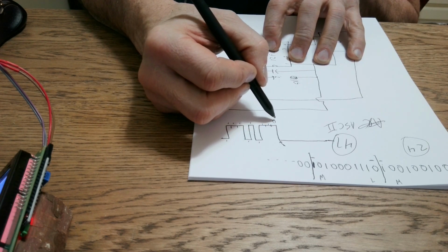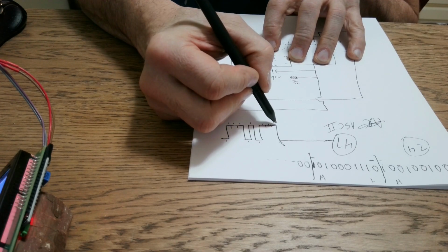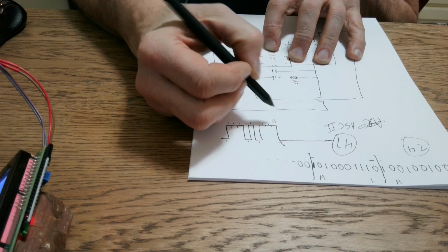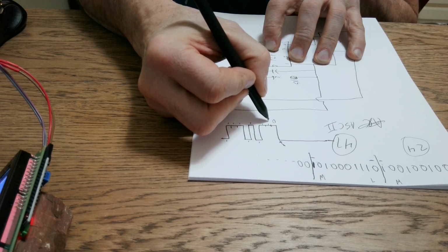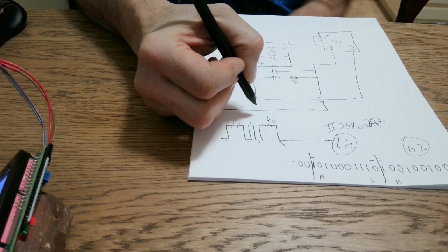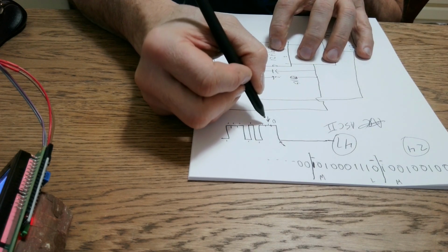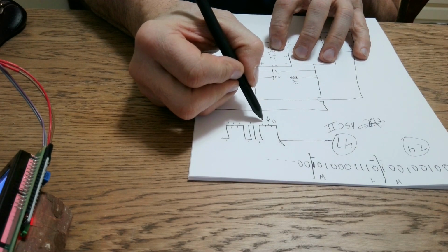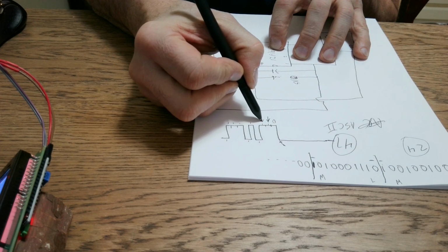The first one I don't need to read. I know it is a 0. So I'm going to go right over there and then right in the middle of this. If it's 100 microseconds each, I want to read at 150 microseconds. Right there will be my first read. And then every 100 microseconds after, I will read the pieces of content.